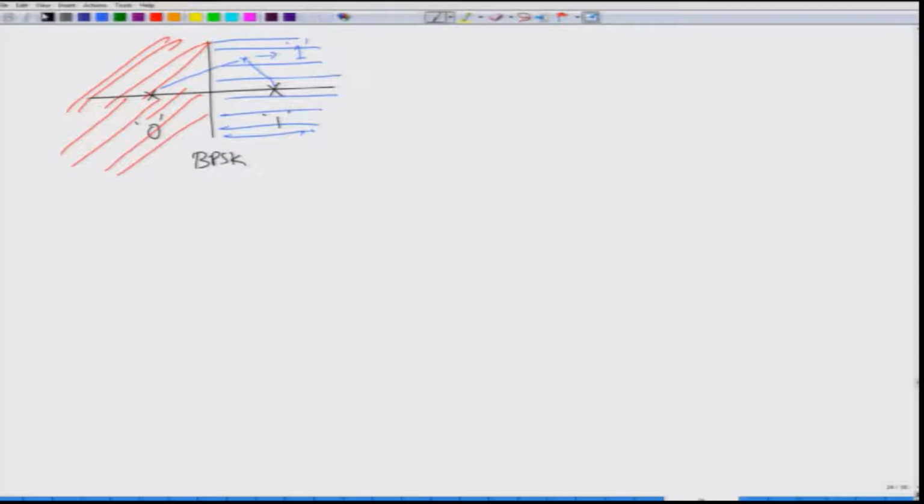But interestingly, let us say you have a BPSK transmission and then you have some phase noise. What the phase noise does to the BPSK signal is that it starts to rotate the constellation points. So, the received signal can be lying anywhere on this circle, depending on how strong your phase noise is. One can see that to completely cover the circle means that the phase noise has to be large. If the phase noise is not very large, then it would be only over one particular section. So, let us say over this segment your received signal can lie anywhere, but still notice that you are not making any errors here.